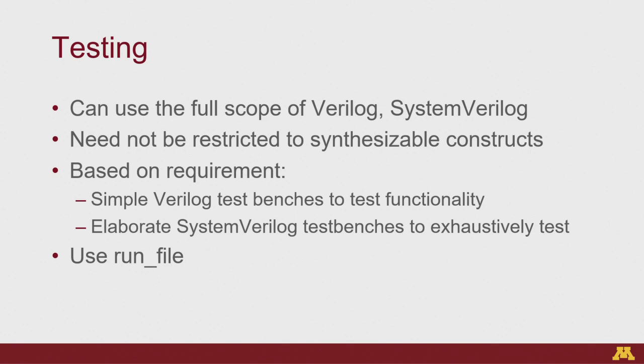If from the top level you just know what the input is and what the output is, that's the only thing you care about, right? So essentially a test bench just does that. It throws some input into your design, then checks the output it got back and says, is that the correct output? So let's say, for example, I'm implementing a filter, I know for this sequence of inputs what the output of the filter should be. And all I do is feed in the input, get the output from the block, and compare it one item at a time against my expected value from the filter. Right?